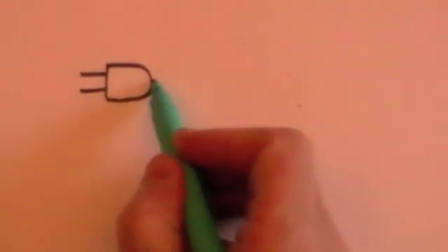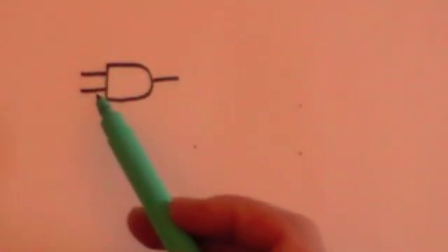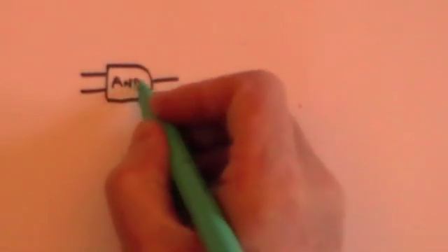We've already described the AND gate, which you'll remember has the symbol like this. And in principle what it means is that you only get an output if both the inputs have got a voltage on them. So that's the so-called AND gate. There's another gate which has a different shape, and that's called the NOT gate. What that does is it says if you've got a positive voltage of say 5 volts on the input, you get no output. If you have no input, you do get an output.